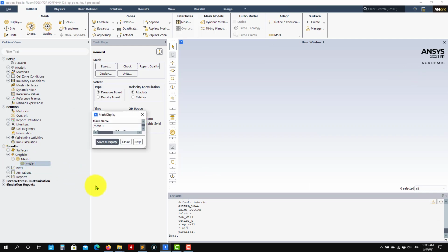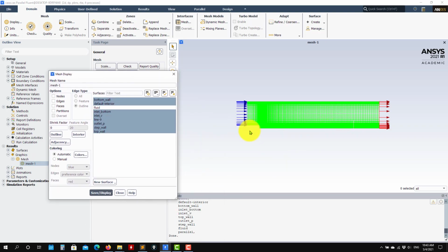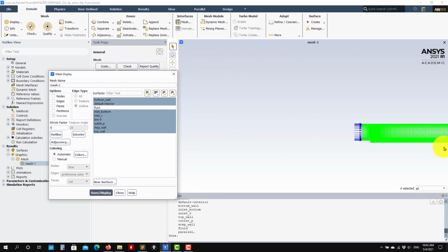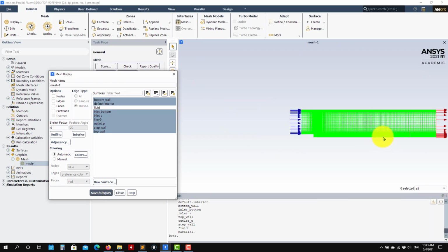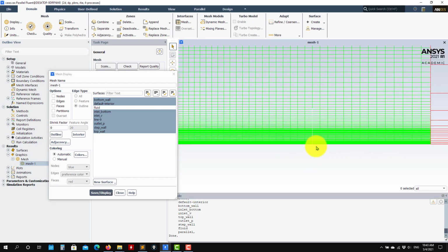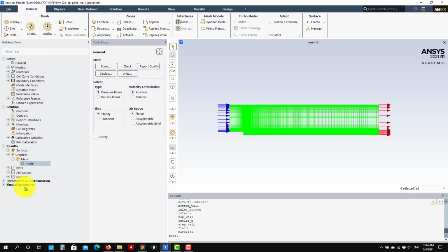As you go here to mesh, this is our mesh. As you see, this is a nice, fine mesh. So it's wall resolving, and let's run it to see what y plus value we have. But also see this line here that we already saw, where we're going to do the sampling. Everything is pretty much set for you already. Remember that we have the vertical approach, so I'm just going to browse fast here because we know what is going on. So general, steady case.